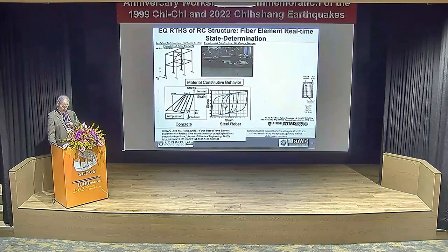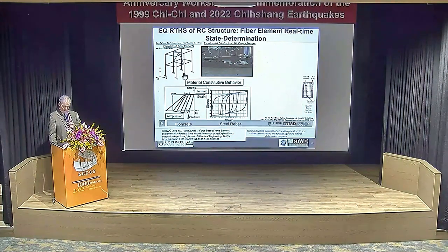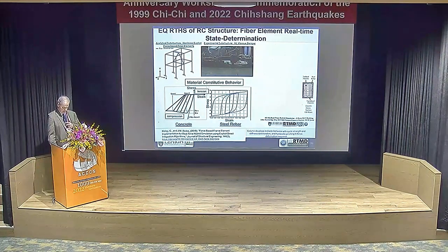This is how this works in real time. We have a reinforced concrete structure. I think it's 28 members; it's too early this morning to count. We're just going to put a damper in the top. This is really trying to test out the element, subjected to bidirectional motions. Here we have the Kent-Park model for the concrete and Menegotto-Pinto for the steel. It's 108 fibers in the cross section. We have the core, the confining core, and the outer core. They're modeled differently, not necessarily using the same parameters, of course, and reinforcing.